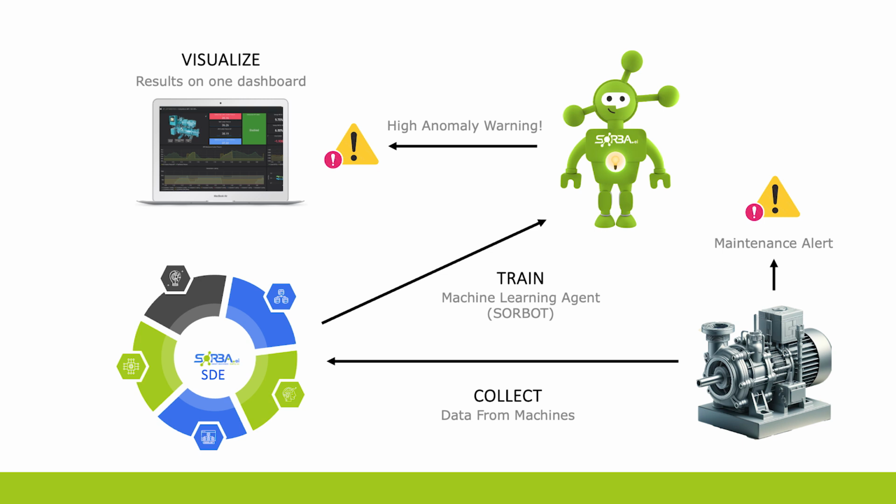Once that agent is trained, the auto learning feature allows you to automatically retrain that model. That retraining can be based on several approaches. You can use it strictly as a button for an operator to trigger that retraining. All he has to do is switch it on, and the retraining will automatically take data, retrain the machine learning model, and then decide whether the new agent is better than the current agent that is running in the system. And if that agent is better, it'll replace it, put it online, and then wait for the next trigger.